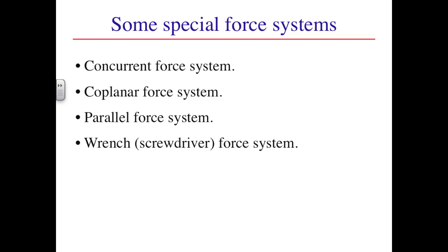In the most general three-dimensional case, it is possible to reduce the equivalent load system to a single resultant force and a collinear resultant moment. This latter combination is referred to as a wrench, but the collinear pushing and twisting make it more analogous to the loads applied when using a screwdriver. We begin by discussing some special force systems, the concurrent, coplanar, and parallel force systems. These will all be reducible to a single resultant force.